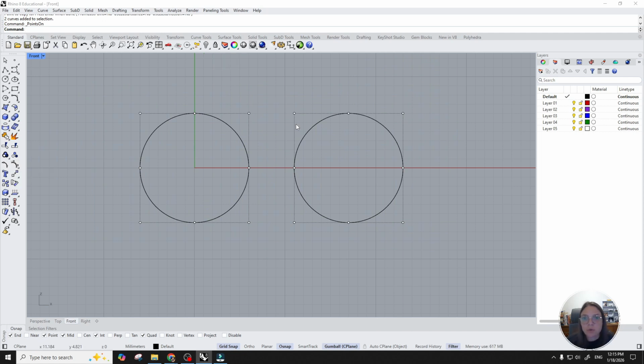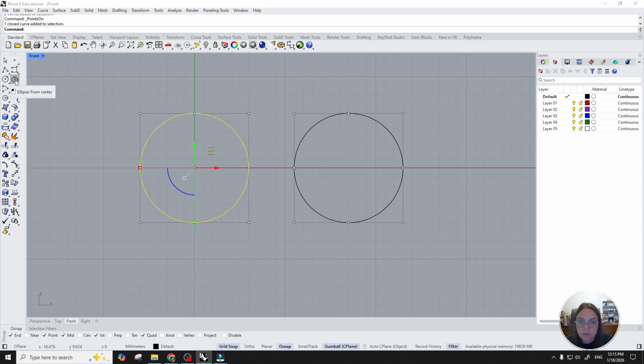And now I want to show you first the difference in the degree, because it will change a lot the way that the shape is going to look once we build it. So if, for example, this round circle here, when Rhino calculates circles, arcs, ellipses, those closed or open curves, it will calculate them as degree 2.